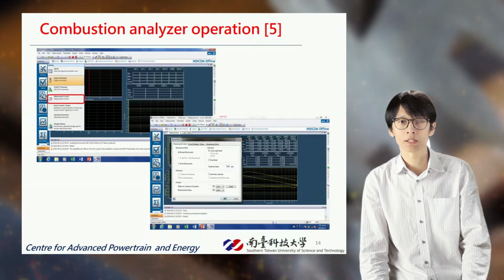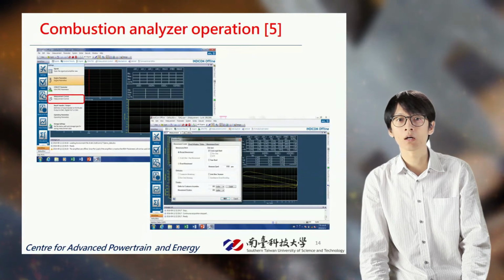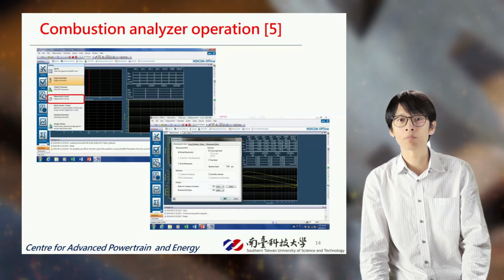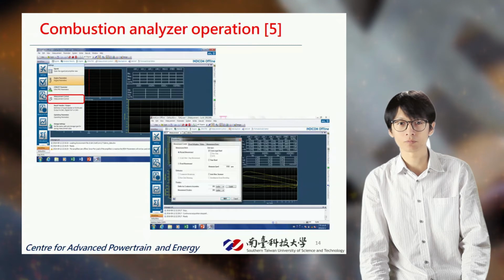Major control setting. In the control mode, select the normal mode. Enter the data of the maximum crank angle and the maximum engine speed. Then enter the duration of 200 cycles. This number can be changed if needed more cycle.